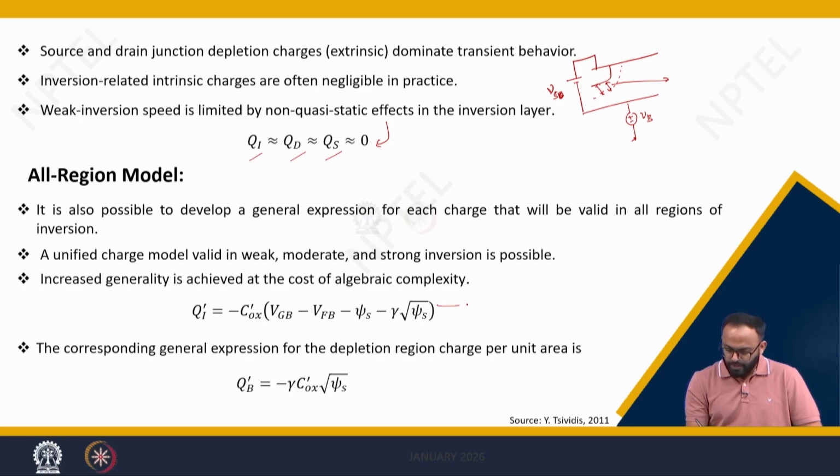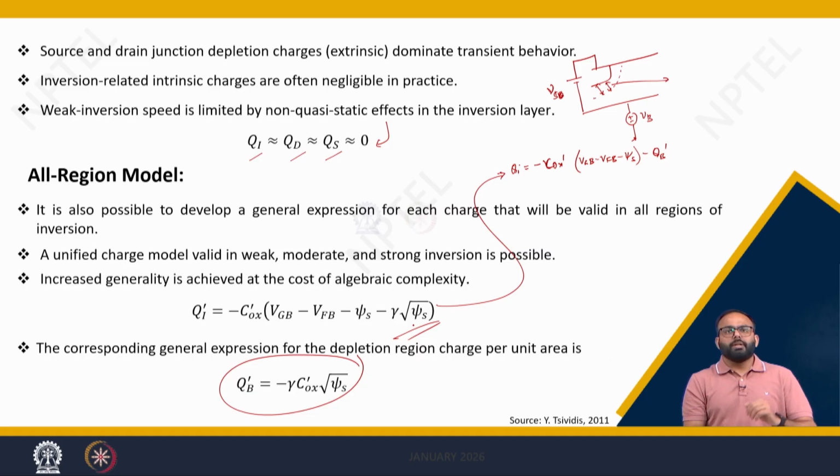So yes, we will use the general expression of inversion charge, which is nothing but minus COX dash into VGB minus V flat band voltage minus psi S minus QB dash, where I am putting the QB dash as this, and you will get this expression. This expression many a times we have used in our previous analysis.